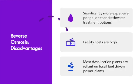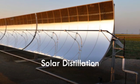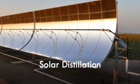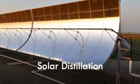However, it does have its downsides. For example, reverse osmosis is significantly more expensive than freshwater treatment options, and the infrastructure is very expensive to build. Another downside is that many reverse osmosis plants are powered by electricity from fossil fuels. This source of energy is not sustainable. A possible desalination technique that could be sustainable long term is solar distillation, which is similar to thermal distillation but uses renewable energy from the sun to heat the water instead of fossil fuels.